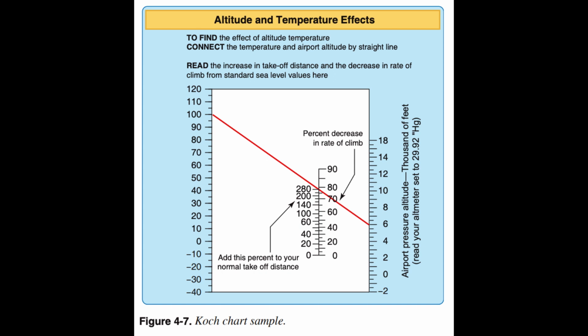However, if the actual temperature is 20 degrees Celsius, 11 degrees Celsius more than that predicted by ISA, then the difference of 11 degrees Celsius is multiplied by 120 feet, equaling 1,320. Adding this figure to the original 3,000 feet provides a density altitude of 4,320 feet, 3,000 feet plus 1,320 feet.